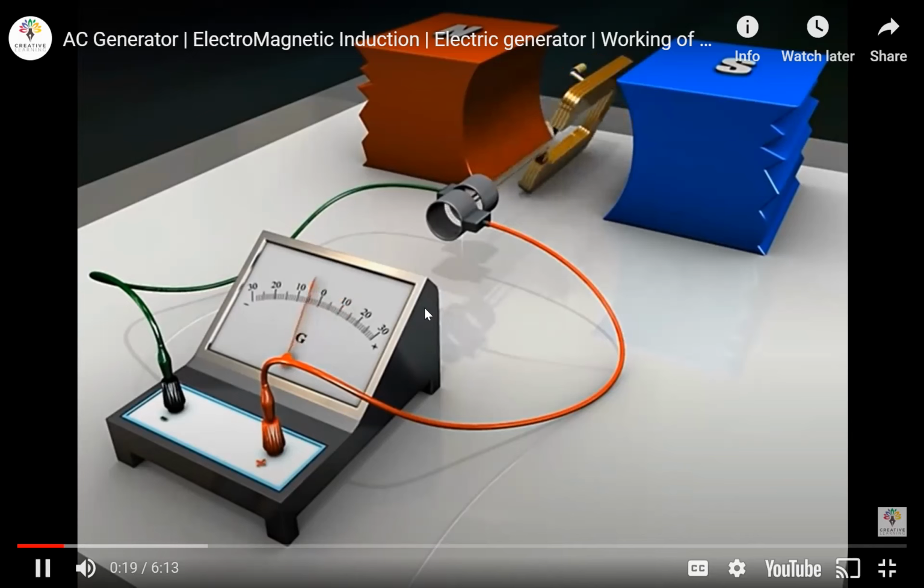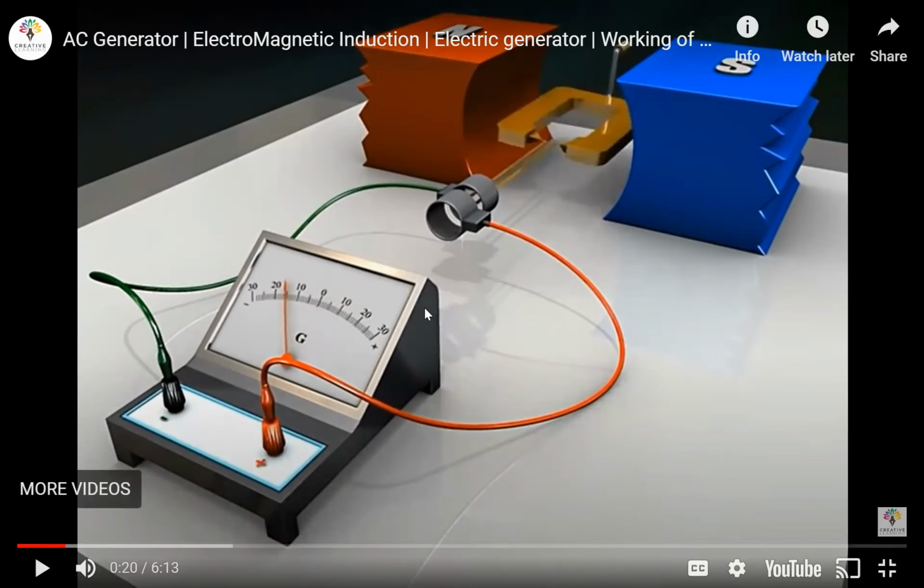EMF or alternating current. And you'll notice the ammeter, this one here is a galvanometer. A galvanometer is basically a very, very sensitive ammeter, so it doesn't really matter, it will still record the same thing. You'll notice that the galvanometer keeps deflecting left and right, indicating that the current keeps going left, right, meaning positive, negative, which is a form of alternating current.